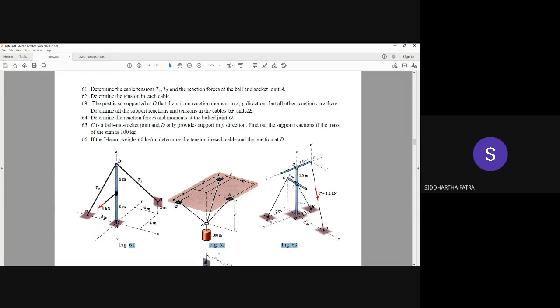Others simply put all the forces, and moments if there are any, correctly, but without any dimensions. Both are incorrect. I should be showing all the coordinate triads, all the dimensions, and where this tensile load T1 is going from point B to point D. I should be showing that direction as well.